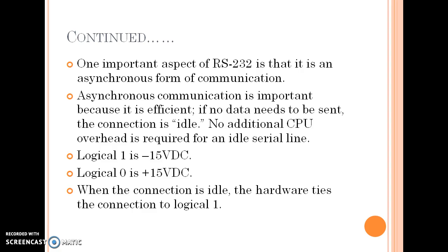The transmitter and receiver operate independently. In case of asynchronous transmission, the transmitter sends data at any time and the receiver is ready to accept that data all the time. And there is no need of a clock signal because synchronization is not needed in case of asynchronous communication. But during the transmission, the format and transfer rate of data must be matched.